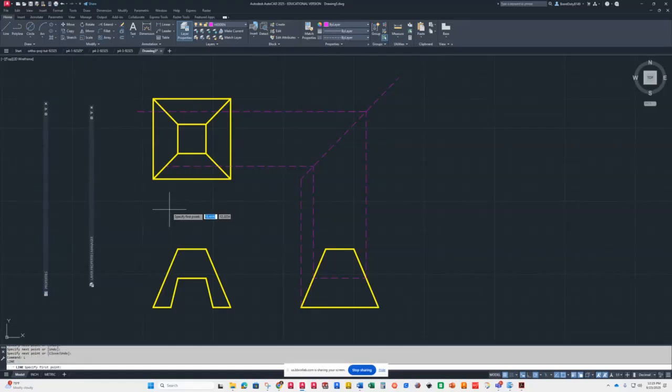So then what you have to do is draw lines. And I should be in a different layer, so let's go back to object layer. So I need to draw from here up to there, and from here up to there, and then I can draw that line. And then I need to draw this guy, and then draw this guy.